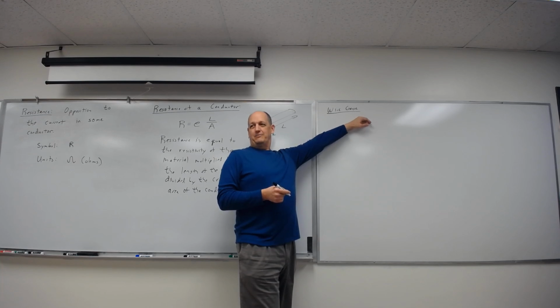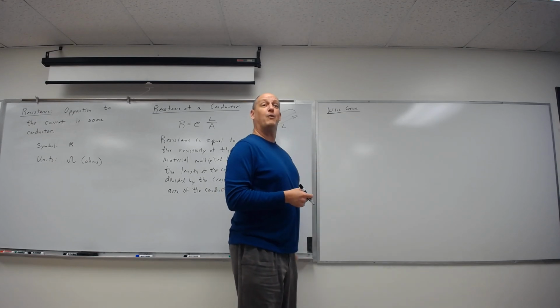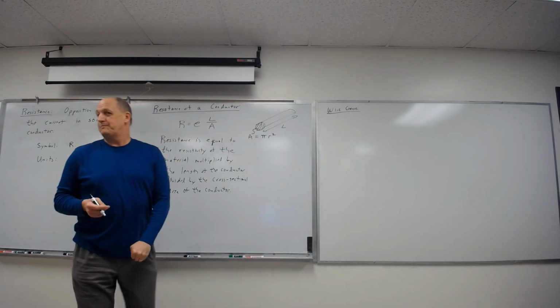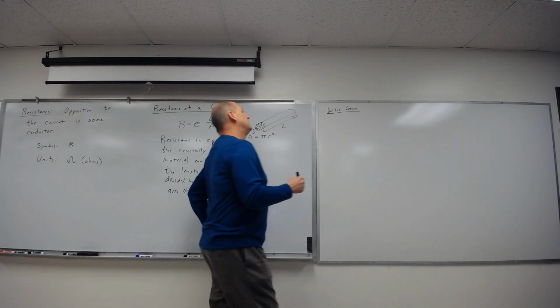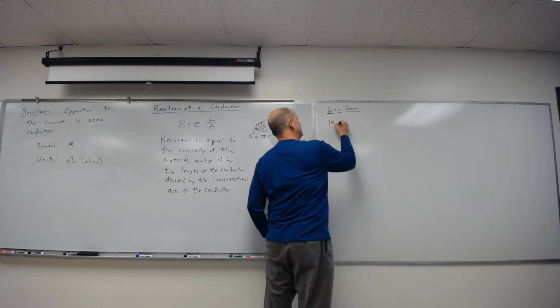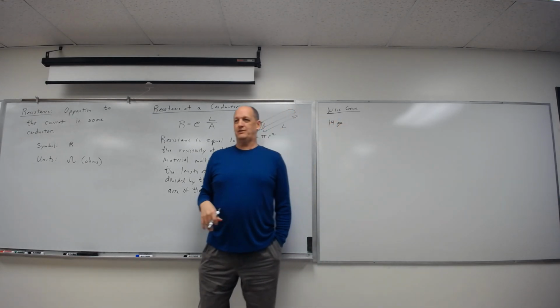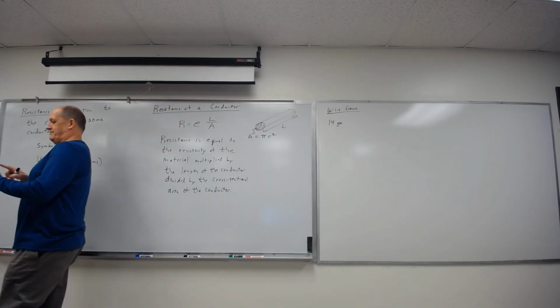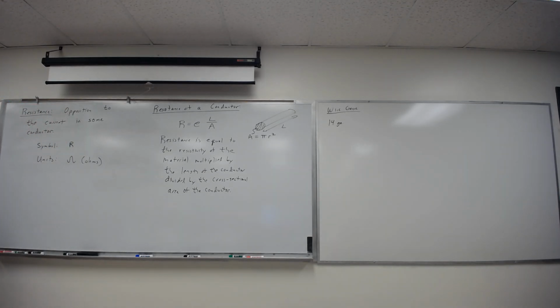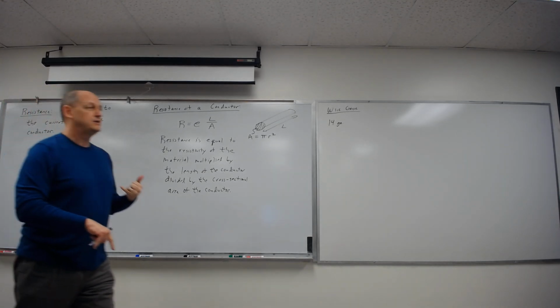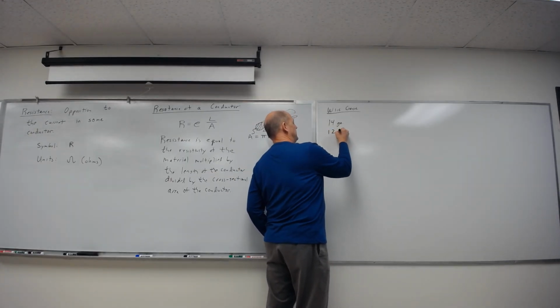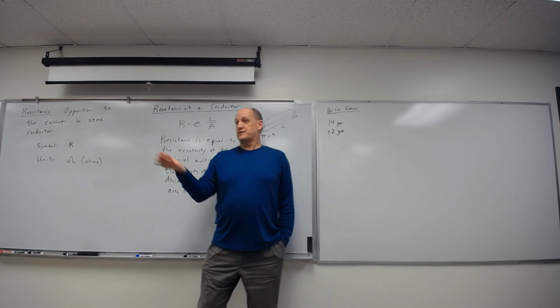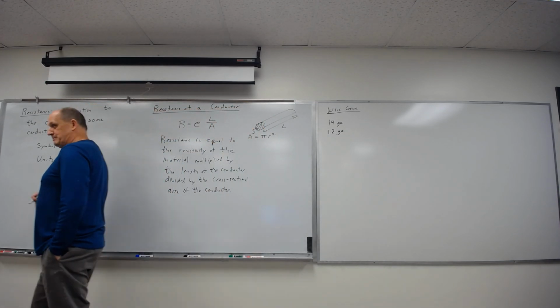Just like a shotgun for the bird hunters in here, right? 12 gauge is bigger than a 20 gauge. Same with wire. So, standard household electrical wire. 14 gauge is what you'd put on a 15 amp circuit. Standard lighting for a house, standard room circuit for older houses. Now most of them have gone to 12 gauge, 20 amp. It's what you use on those 20 amp circuits for your household wiring.